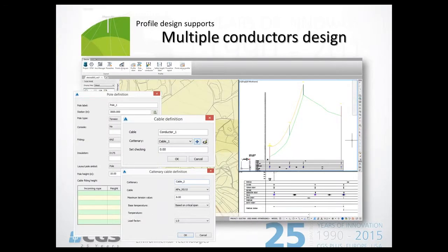After the power line has been designed, a profile gets drawn, and what's important is that all the masts, so the poles at the beginning of the power line and at the end, and all the poles where this power line has a PI, so it has an angle, are automatically defined already and are inserted in the profile. So the user just needs to add the poles in between those poles.